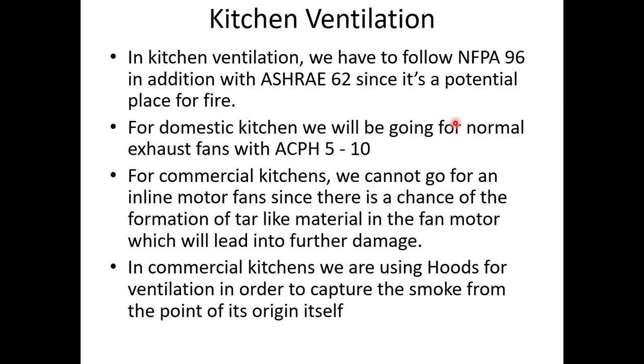So while implementing the ventilation systems, you need to consider the NFPA 96 standard, which is for fire-prone areas. You have already seen this kind of standard in the firefighting study. And for a domestic kitchen, we can simply use an exhaust axial fan, similar to the domestic restroom arrangement you've seen. So even for domestic kitchens, you can go with the same method itself.